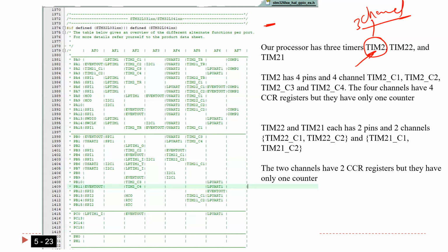Okay, guys. But what I want to say is, all the time I was explaining, I assumed we have 1 timer. In reality, we have 3 timers, not 1. You get what I'm saying? That means I can use every timer, so 1 timer has 4 channels. The other 2 timers have 2 channels and 2 channels. Every channel can be input capture or output compare. Oh my goodness, you have too many things. Yes, you have too many things. So for example, one timer will have 4 channels, so I can use all of them as output compare or all of them as input capture.